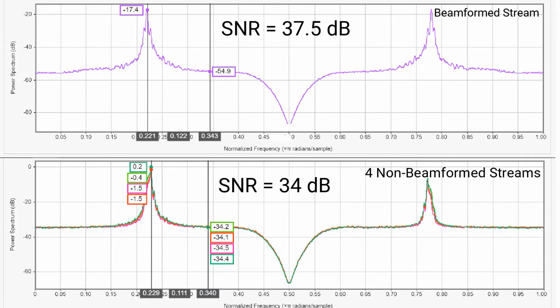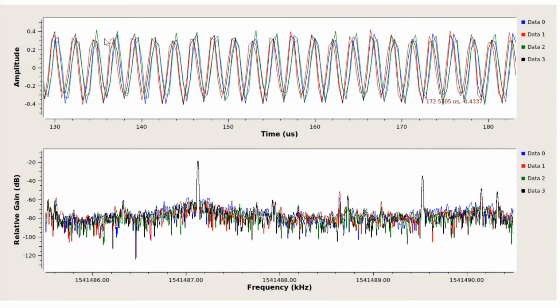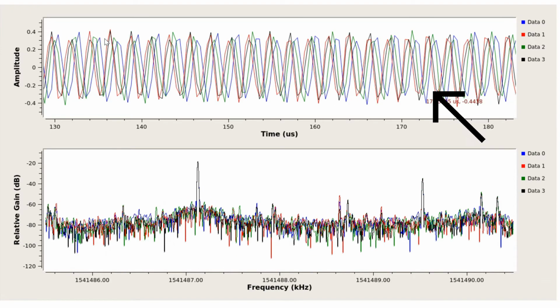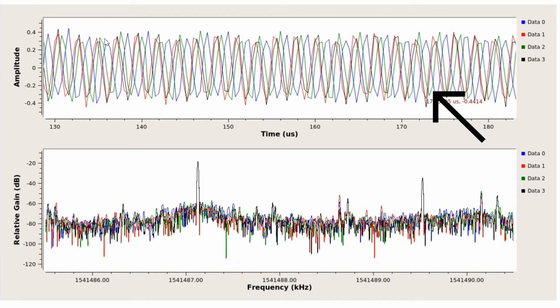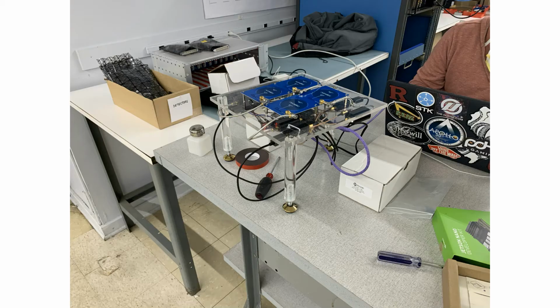We used a GNU radio block called multi-RTL to account for the initial phase offset of the SDRs. However, while looking at our recordings, we noticed that the SDRs would eventually suffer from phase drift. If we could modify the multi-RTL block to resynchronize whenever this happens, we believe that our system could perform even better. In an effort to continuously improve, we have already developed design modifications to our system.